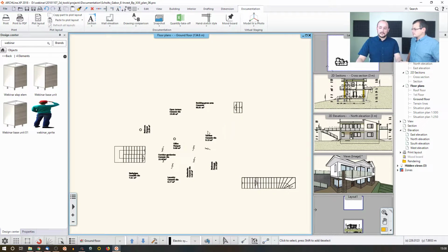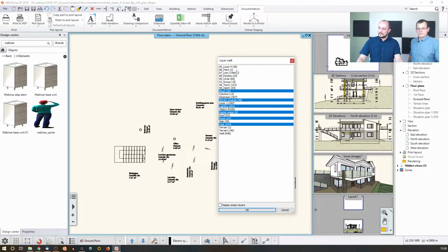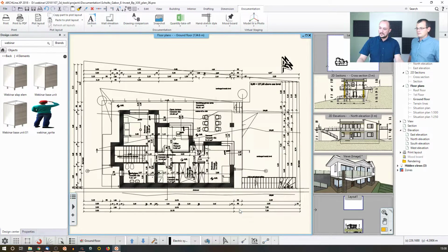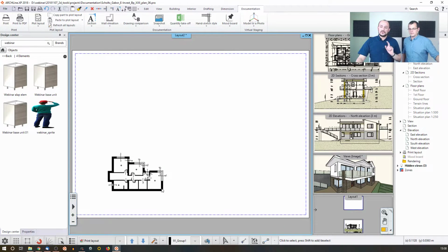And that's the whole point, because I have the world where I'm working in. Let me just enable everything. And I can decide what to work with, and then I can be sure that whatever I do on this content, it won't change the way I look at that content here. So you don't lose any data. So I can easily prepare 2 or 3 or 4 different versions of the same drawing if I already organize them well using the layers.